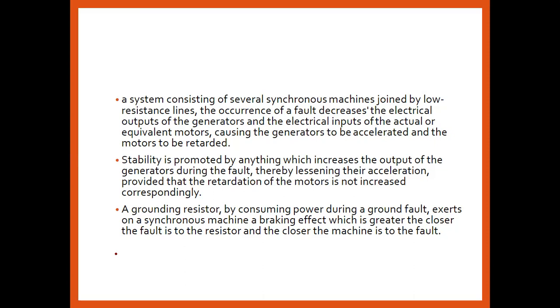Means whenever several synchronous machines are connected in parallel on the infinite bus, if a fault occurs, obviously the electrical output will be directly affected. If the electrical output is affected, the balance with the input is affected, causing the generator to accelerate more and more, and it causes the motor to be retarded.